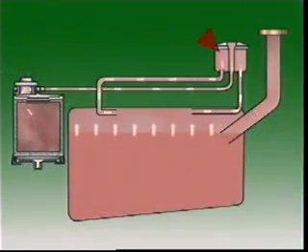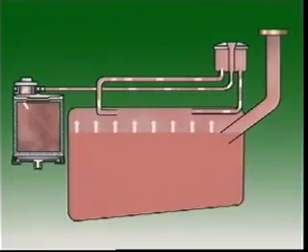Some systems have a small container called a liquid vapor separator above the fuel tank. It also prevents liquid fuel reaching the charcoal. This petrol tank has a small separator tank and a number of vents. They're from different parts of the tank, so that for as many vehicle positions as possible, at least one is always above the level of petrol in the tank.